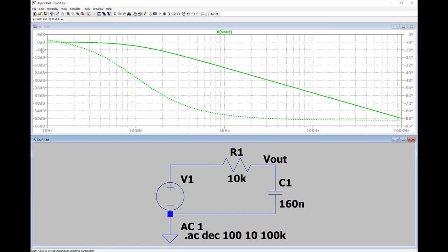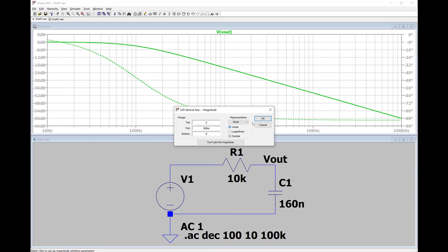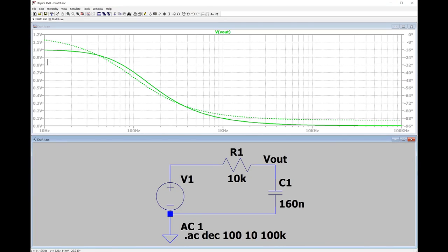To get rid of that, right-click that axis, choose linear, and then it will have more familiar types of units. So if you put in a 1 volt, 10 hertz, 0 degree cosine wave, what you'll get out will be this solid waveform in magnitude and this dotted waveform in degrees in phase offset that you can measure on the right. So put a 10 hertz, 1 volt input, and you'll get a 1 volt, 10 hertz at, bring the dotted line over at just less than 0 degrees offset. So maybe it's going to be, you put in a 1 volt cosine, 10 times 2 times pi times t plus 0 degrees, you get out a 1 volt times cosine of 10 times 2 times pi times t minus maybe 6 degrees.